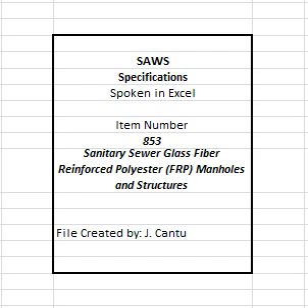853.5 Construction. 1. Manholes and structures shall be constructed of materials and workmanship as described by these specifications, at such places shown in the contract documents and in conformity with the typical details. 2. Fiberglass manholes and structures must be installed according to manufacturer's installation instructions. Correct manhole installation requires proper concrete foundation, good backfill and proper handling to prevent manhole damage and ensure long-term corrosion-resistant